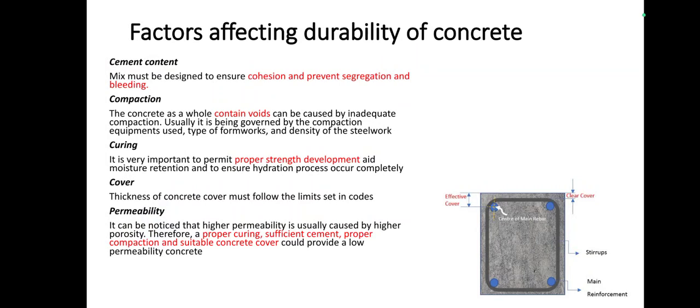Sometimes steam curing also can be given, infrared rays also can be sent. Those are the different methods of curing based on the conditions, or the environmental condition which is available. If you are not doing proper curing, proper strength won't be attained, thereby durability will be affected. And the next one is cover depth. If you increase the cover depth, what will happen? The possibility of air and water from the outside environment reaching the reinforcement will be delayed, so the corrosion can be prevented and the concrete will be durable.